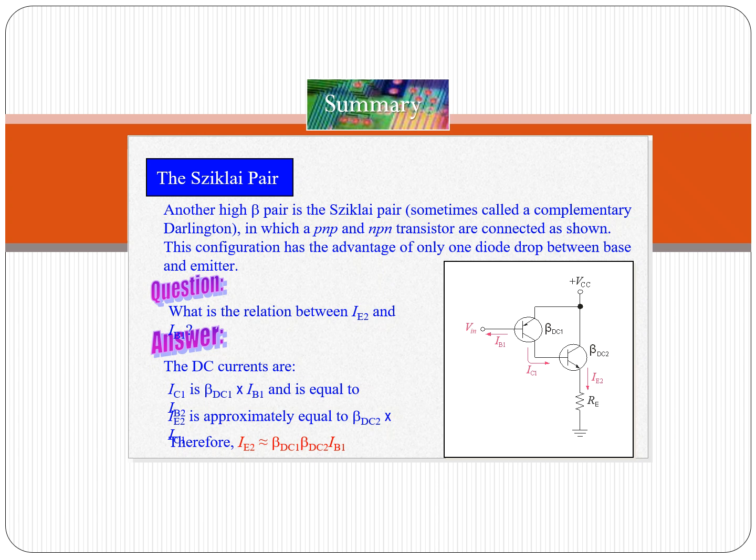So let's go ahead and break this down. For the formulas, if we're looking for IC1, that's going to be equal to beta DC1 times the base current, right? So in other words, DC beta times the base current. IE2 is going to be equal to the DC beta times IC1. And so overall, you can have the I sub E current being equal to beta DC1 times beta DC2 times the current at the base, right? So hopefully I said that correctly.